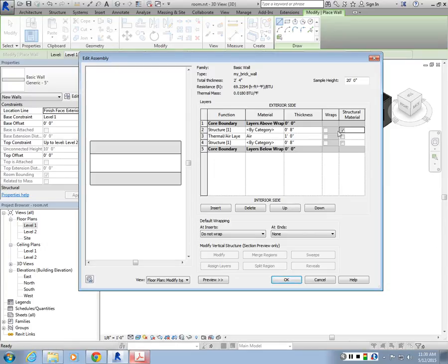But I think this is mostly for you to assign one part of the wall the structural property, so that when you want to extract some properties from the wall, the surface area or the volume of it will be retrieved, right? So let's say how much concrete is in that wall, because there are so many layers to it. You don't want the overall volume of the wall, but just the volume of the structure. So I think this is what it's for.